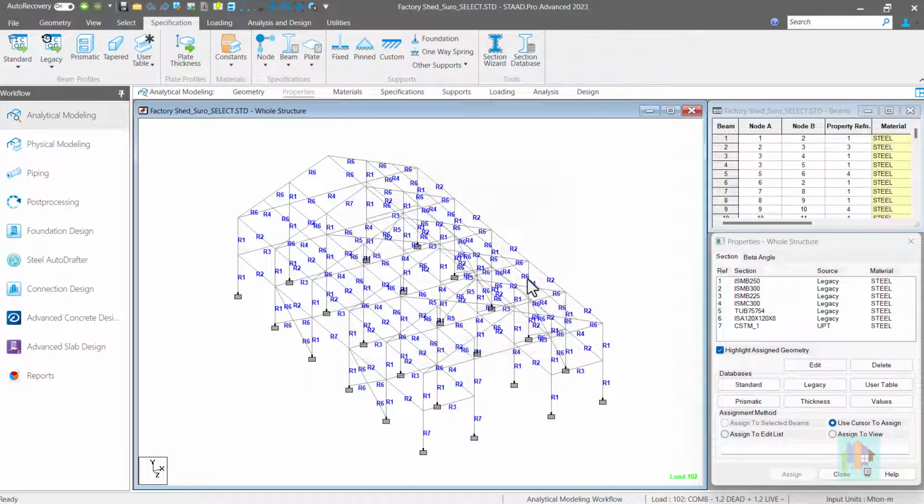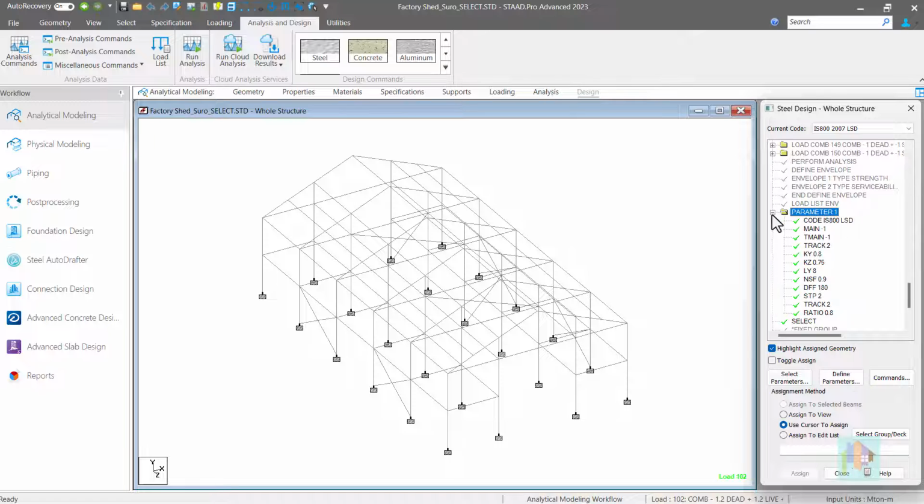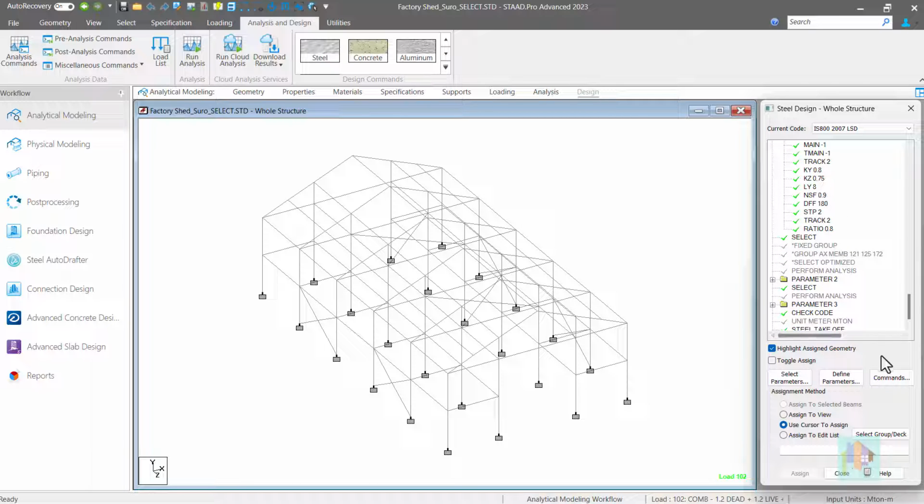That's all about how we can perform steel optimization in STAAD with different commands, parameters and custom databases. With this approach, we can completely eliminate the manual trial and error process and use the optimum section with minimum steel usage in any project. Before we use this optimum section, we need to review the results and check the feasibility and availability of the sections.